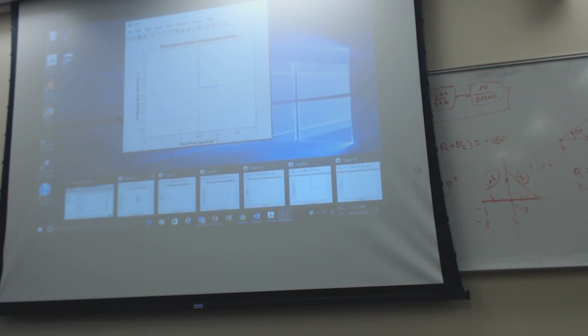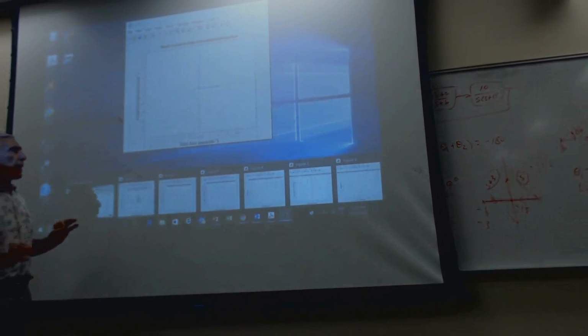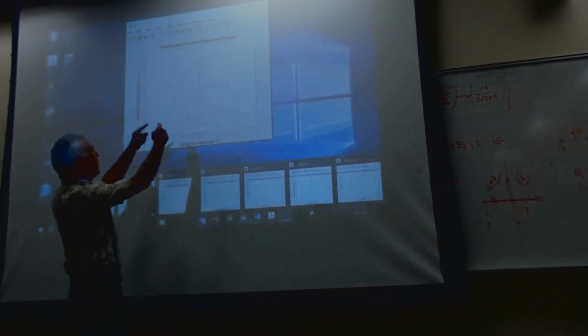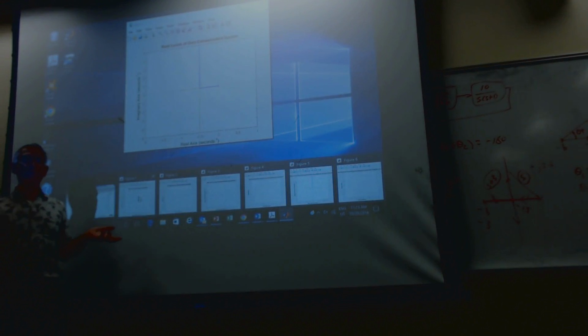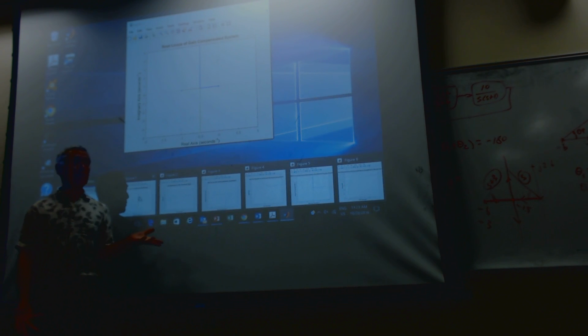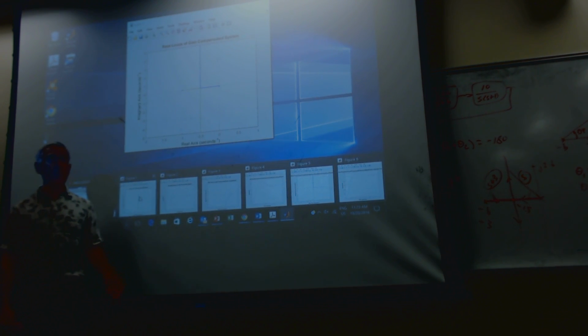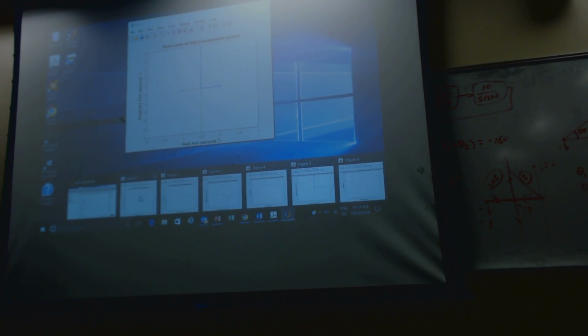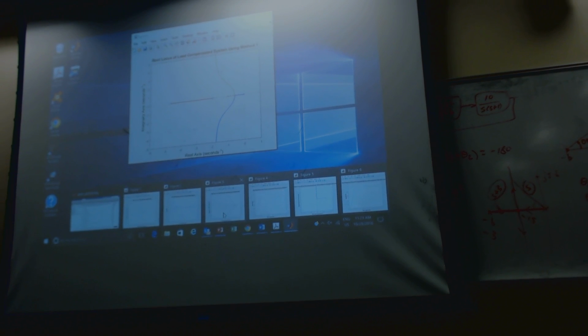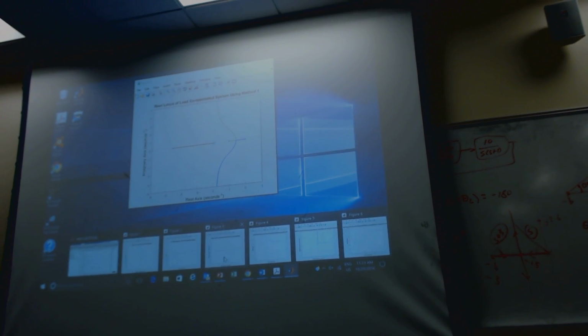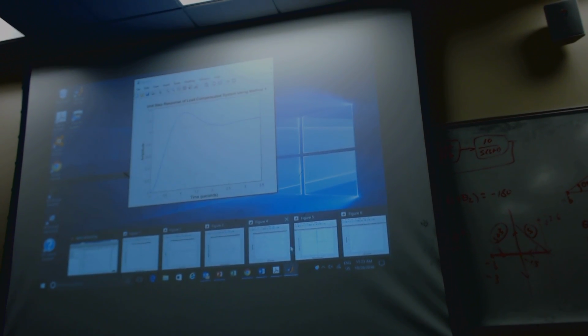that's the original root locus, right, was pure gain compensation. It just goes together, it breaks away at -1/2. And you can't satisfy the spec. The real component of the spec is -1.5. So it can never, using pure gain compensation, satisfy the specification. This right here is using method one. Now, this is method two.